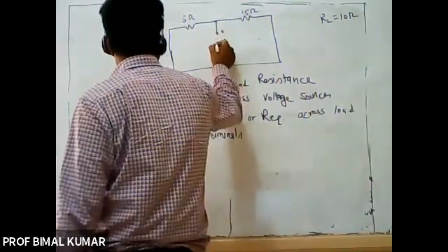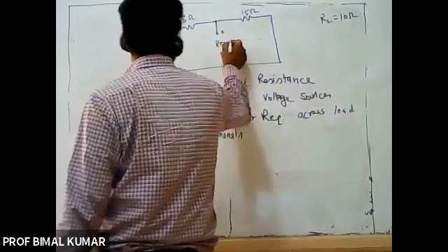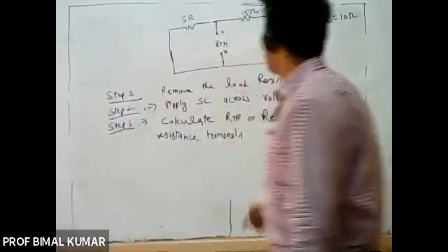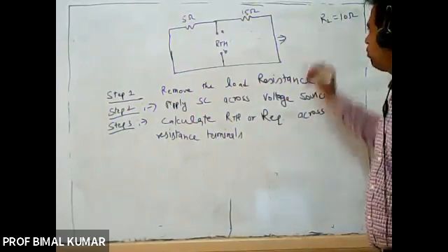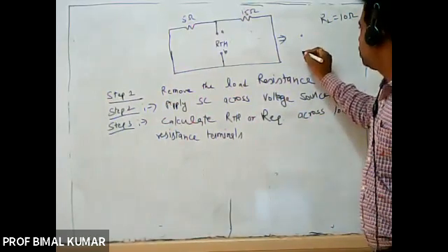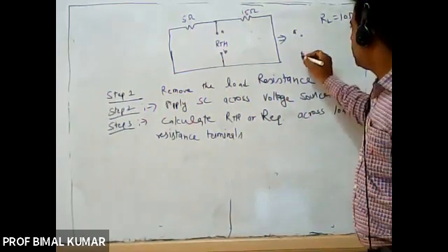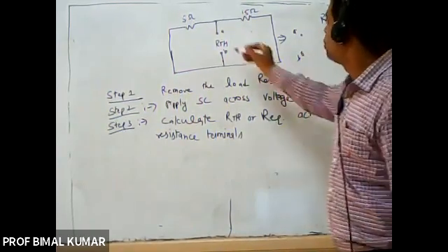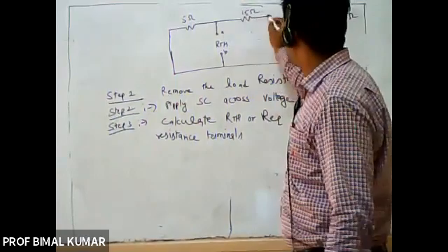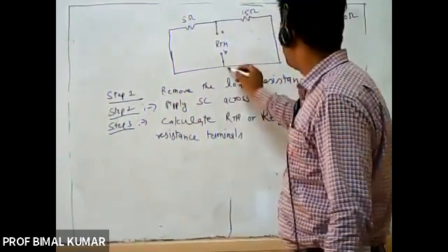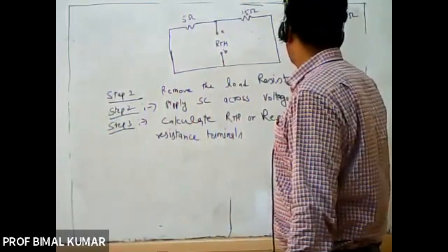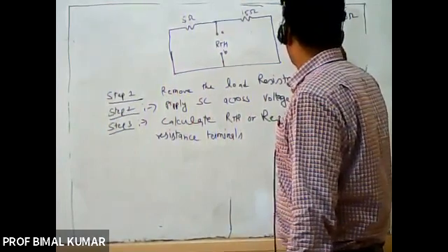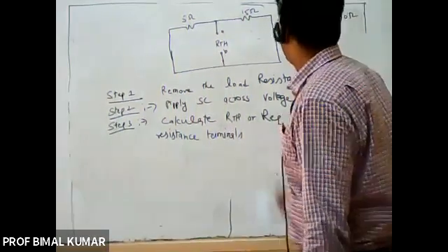So here I will have to calculate RTH. So I'm just going to redraw the circuit by taking A and B at the outer terminal, right? So this is by practice. This is your terminal A and this is your terminal B. So starting from A, 15 ohm resistance, and second terminal of the 15 ohm resistance is connected at B, right? So this is here 15 ohm,